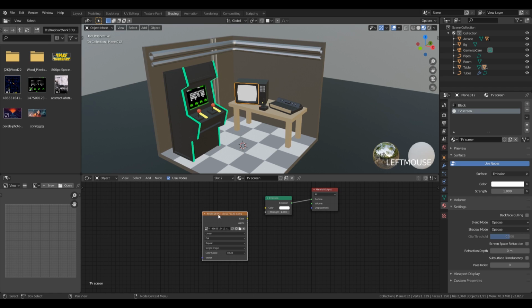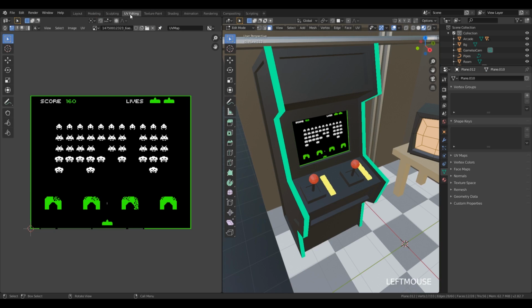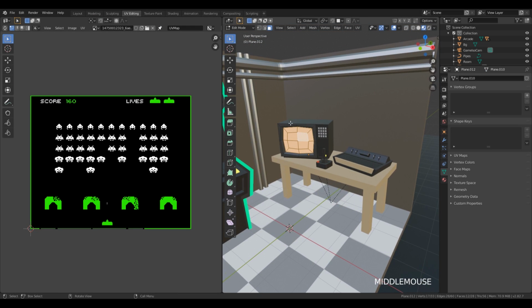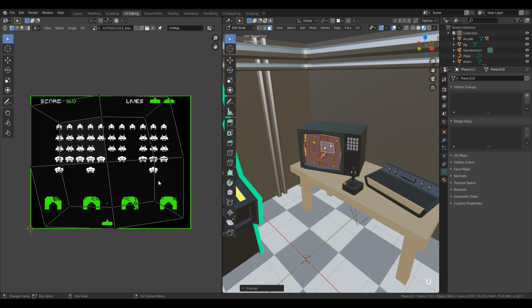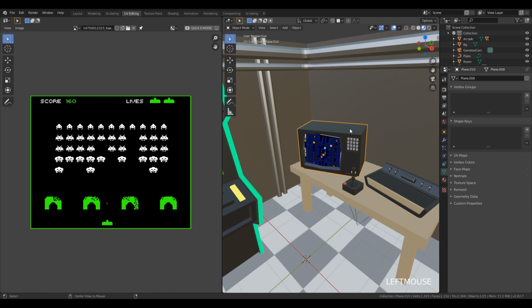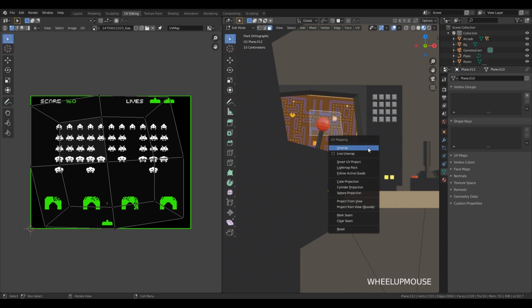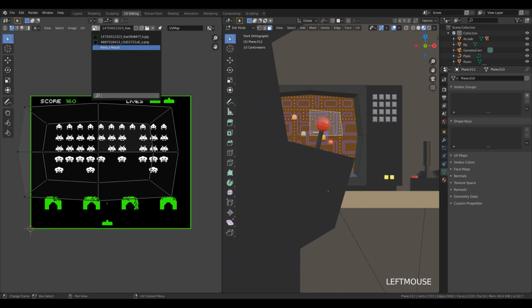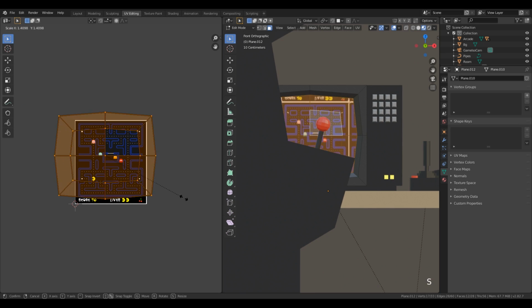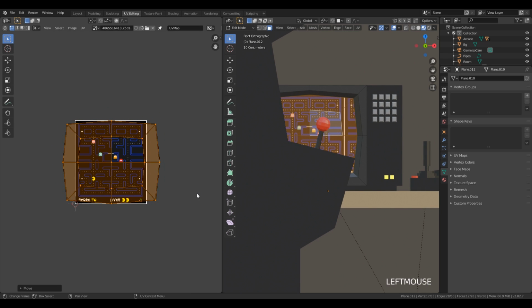And drag the second texture, connect it, go into the edit mode. Let's look at that. You can press U to unwrap, and you can see the rotation is a little bit weird. So what you can do is to actually reset the rotation here. Look from the front, press U and project from view, and you would get the same exact shape here. Of course, we want to switch this to the actual image that's going on there. And we can move this.